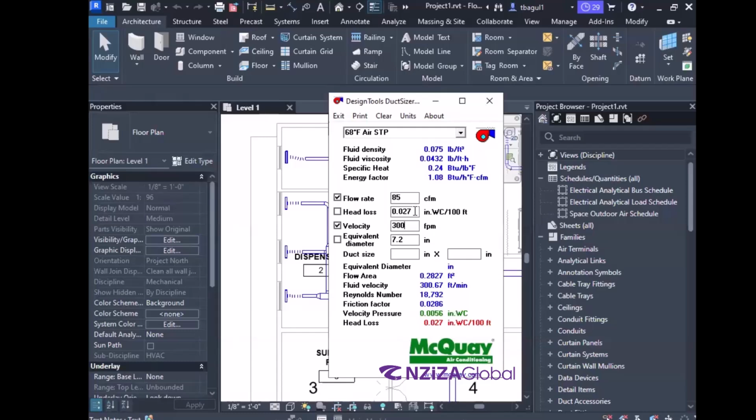But when you make the air velocity as low as possible, please understand your ducts are also getting bigger. If the air has a lot of space to move through the duct, it will not be noisy. The smaller the cross section of the duct, say a 10-inch by 10-inch duct versus a 6-inch by 6-inch duct, and you're trying to push the same amount of air through it, the 6-inch by 6-inch duct will create more noise. That air will have more velocity, making more noise.